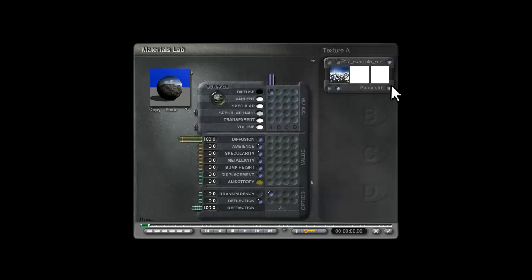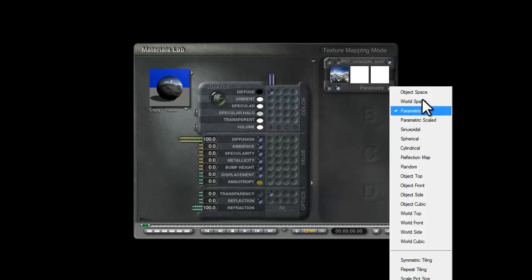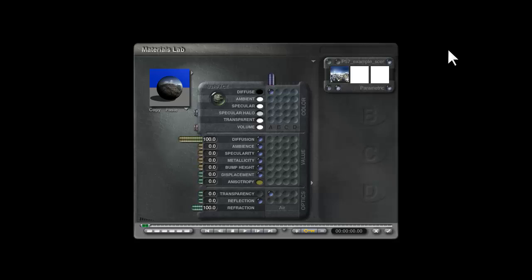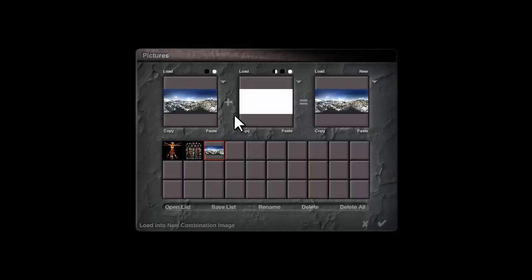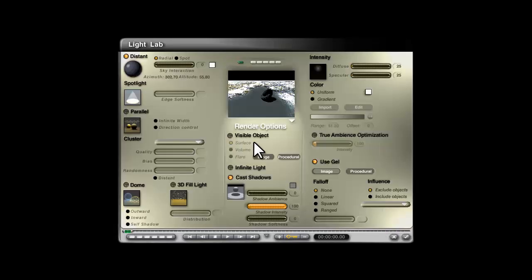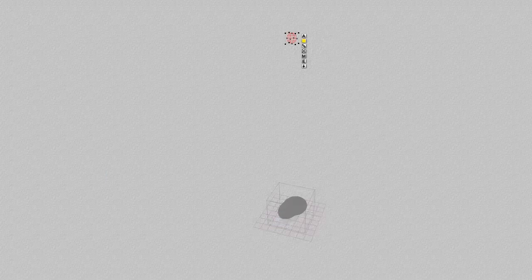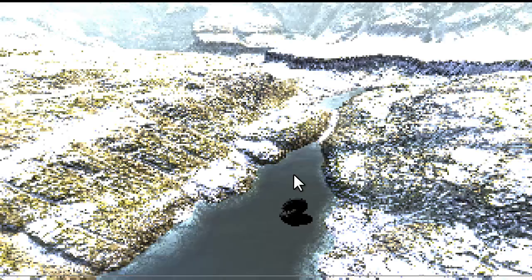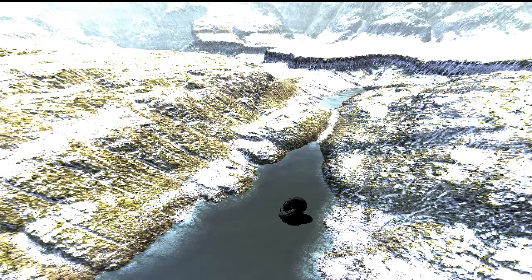The difference between the spherical mapping and the parametric mapping is a rotation of 90 degrees from the point of its origin. So it just depends where the edge starts. So if you find things around 90 degrees out of alignment when you're doing this sort of operation, just see if you can switch between parametric and spherical, and that might solve it for you. Anyway, as you can see in the preview, interesting things are happening. So I'll give this a quick render. There you go.